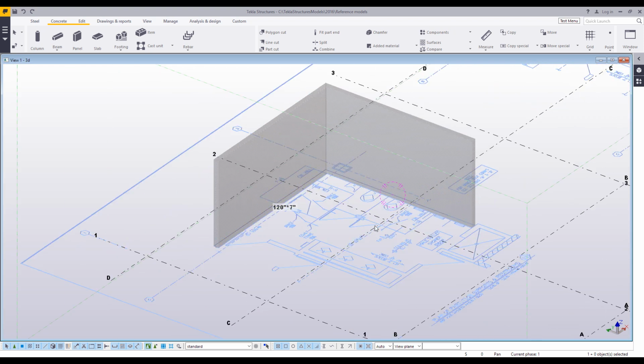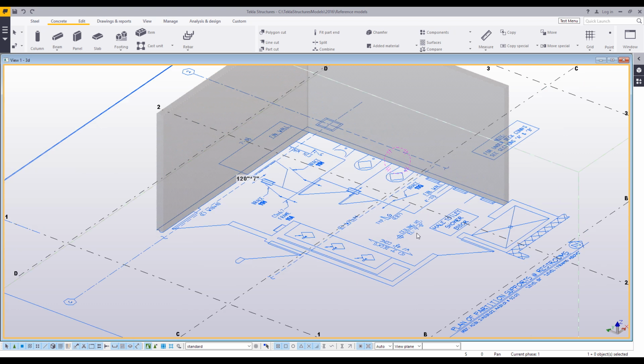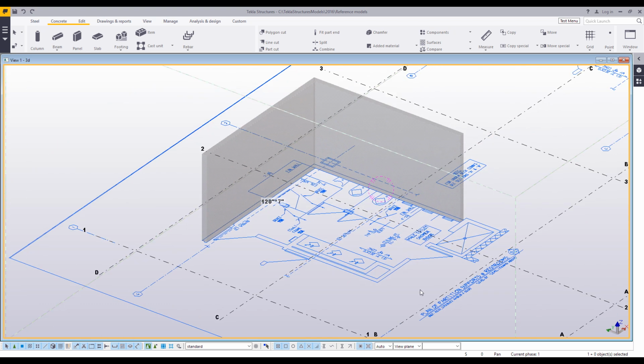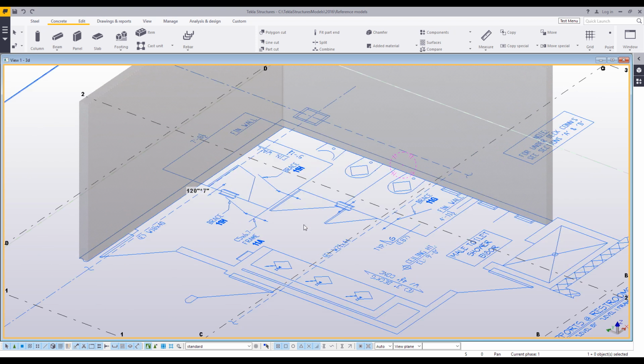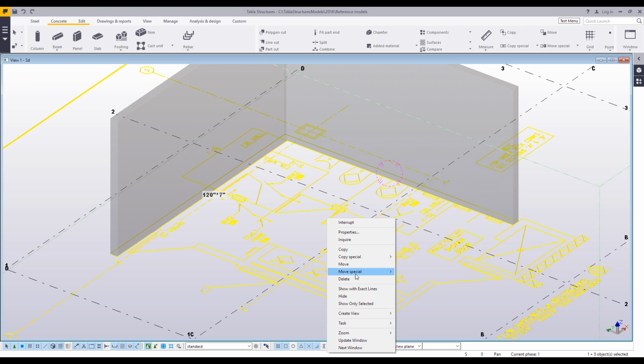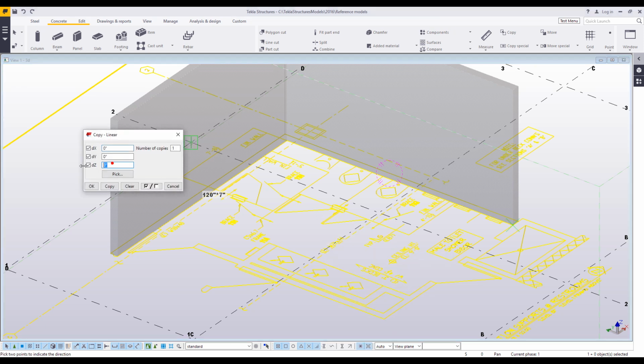So I've created now a wall panel, and if I needed to, I can create a copy of this reference up higher. It says here that the ceiling height is at 9 feet, so let's just say, without having a full set of plans in here, that the actual structural framing, we have some channels being run on the ceiling here, should be at 10 feet. So I'll go ahead and I will copy this up 10 feet.